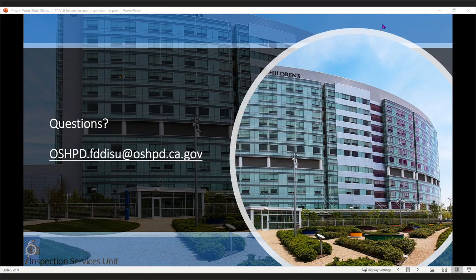Let's zero in on a piece of equipment that has a special seismic certification, just an OSP. All right, let's just use that as an example. Would the IOR need to have that on site? If it's nothing more than a submittal, then I would argue it's not required to. However, reasonable diligence needs to be exercised to obtain personal knowledge.